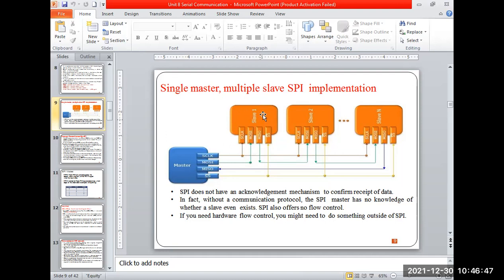This pin is connected to the slave in of the slave device. So if you want to send data to the first slave from the master, it is sent like this. Otherwise, other slaves, or peripherals, send data to the controller always on the line master in, slave out. By enabling the appropriate slave select, if the controller wants to send data to slave 2, the SS bar signal pin of that slave is enabled from the controller, and they perform the communication between the master and the slave. This is the simple working. It can have one slave and one master, or many slaves and one master.